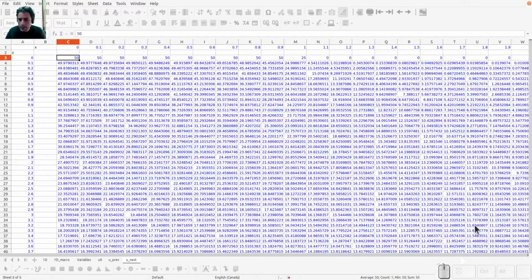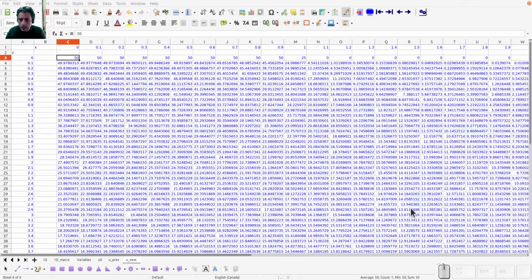Well, we will want to define new sets of boundaries in this case, right? Because in the 1D problem we had no choice. We needed to have the double drainage, so the footing on top we ignored its effect because we assumed that this was free draining, so we had a one-dimensional problem.